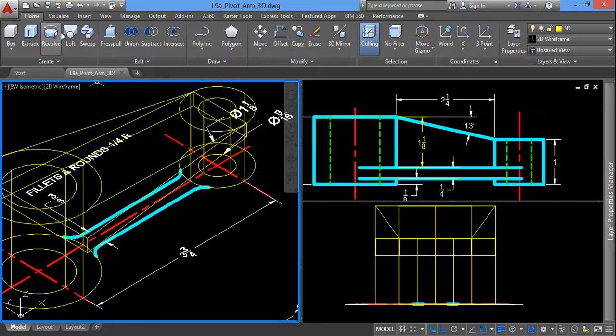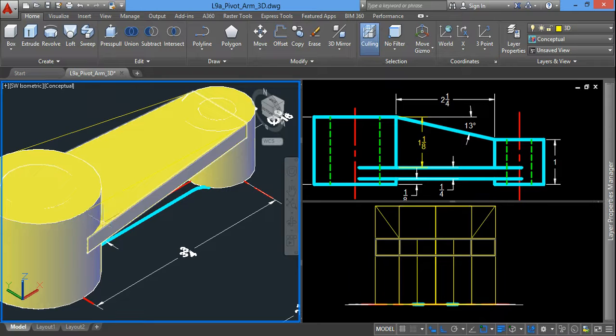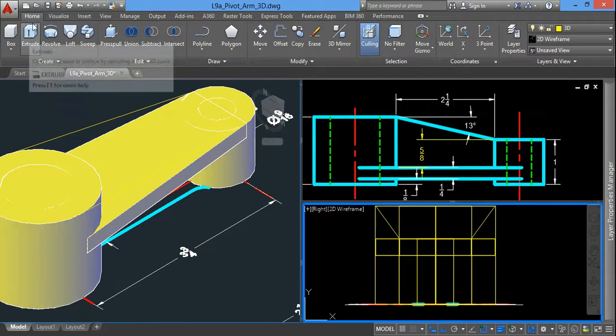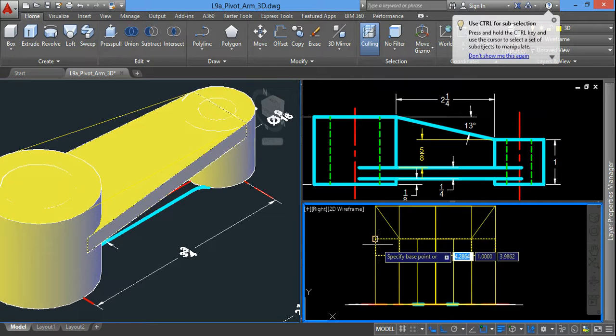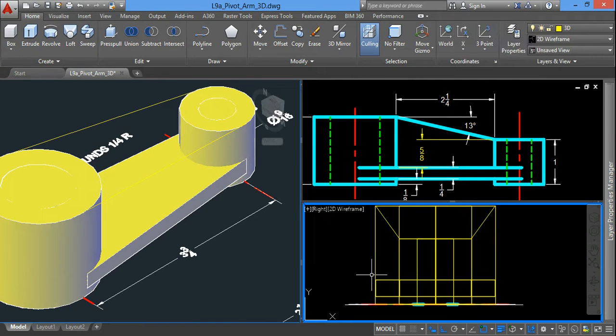Oh, I see. Let me turn on the color here. It's not at the top of this feature, which I thought it was in. It's at the top of the shorter feature, which is over here. So I don't need this 1 1/8, I need this measurement: 5/8. So let's move it down 5/8. Move, select the object, enter, pick a feature of that object, point down, and type in 5/8. Now it makes more logical sense, and it is where it should be, as you can see here.